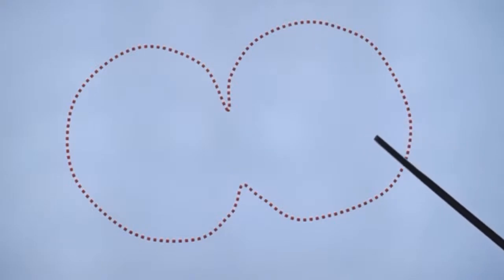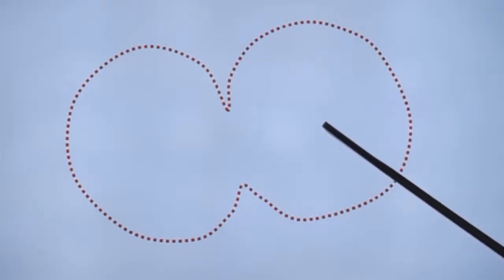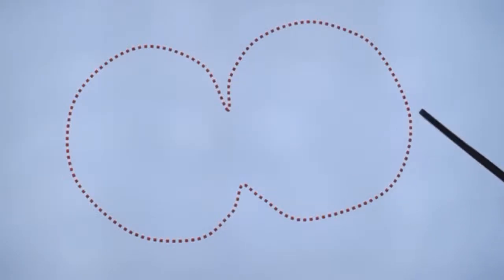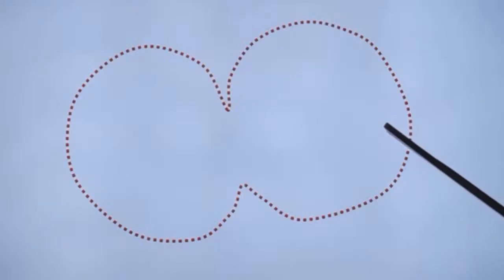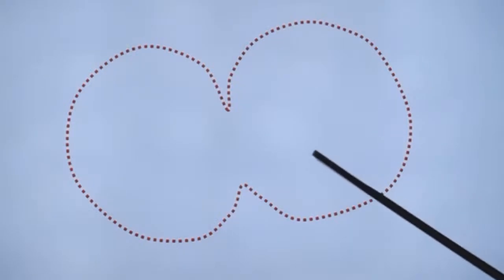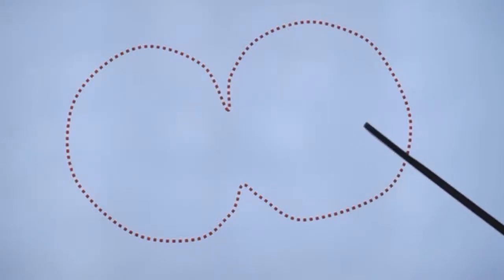But still, this is a compromise antenna for satellite operation because you don't have to rotate the antenna. If you don't have an antenna rotator, a Yagi antenna will work only during a very small portion of the satellite pass, while the J-pole will work almost throughout the pass.